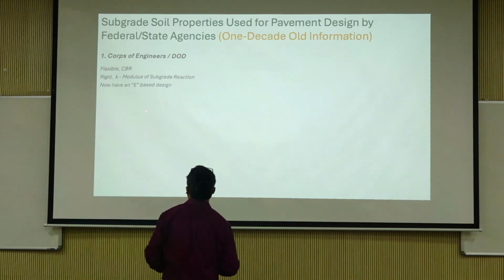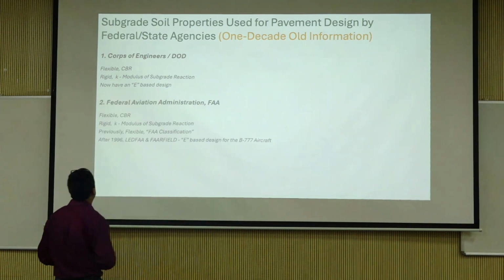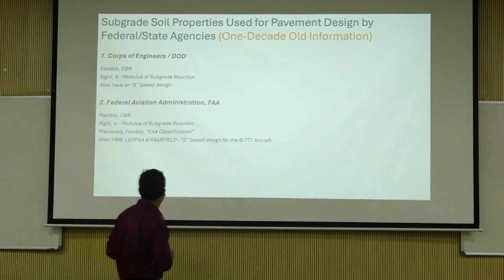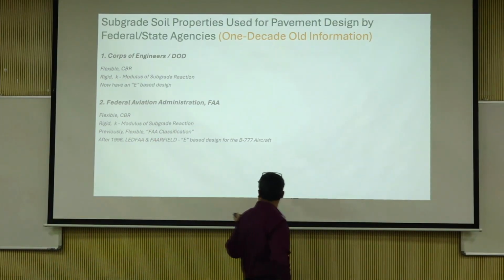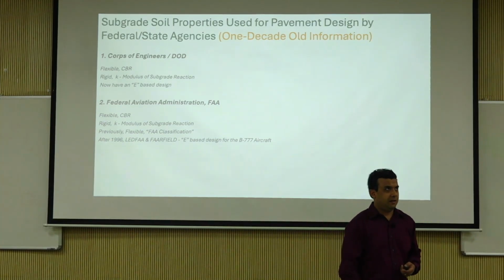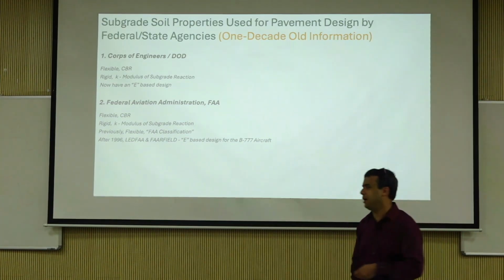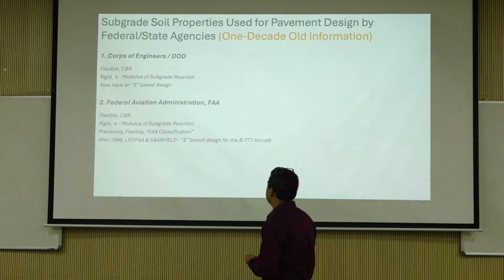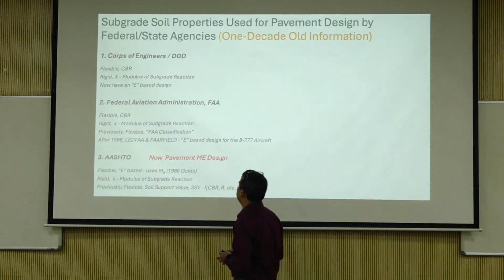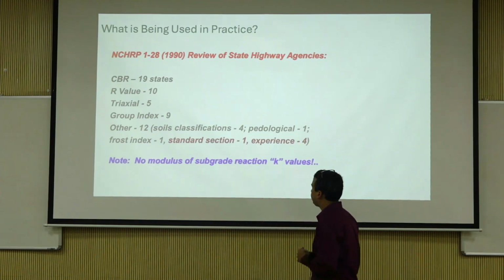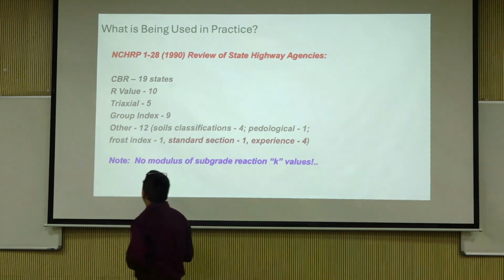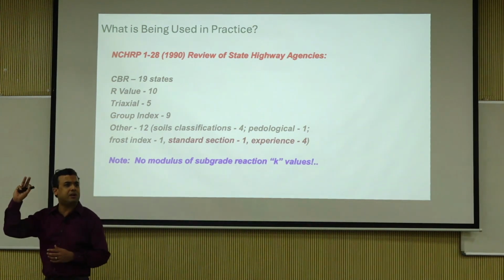So a lot of quick tests, people do modulus of subgrade reaction. FAA, or Federal Aviation Administration, also used modulus of subgrade reaction, and then they have LEDFAA, now called FAARFIELD, I think that's the current name, which is the analysis software. And AASHTO, of course, the ME design or MEPDG, we will talk a little bit about that. So CBR, 19 states were using it. R value, how many of you have heard of R value before?